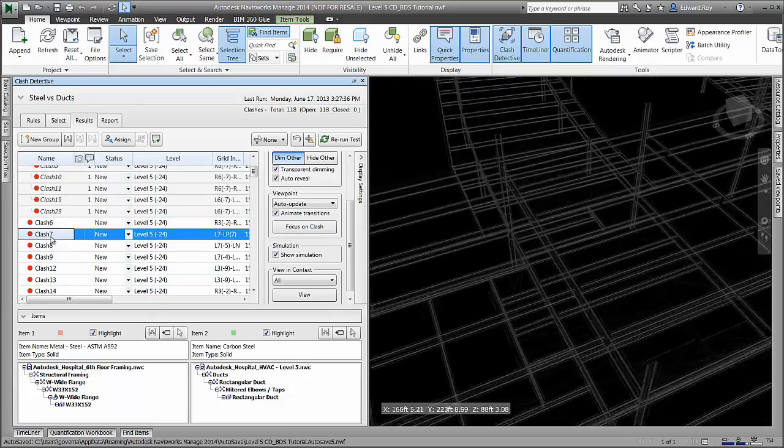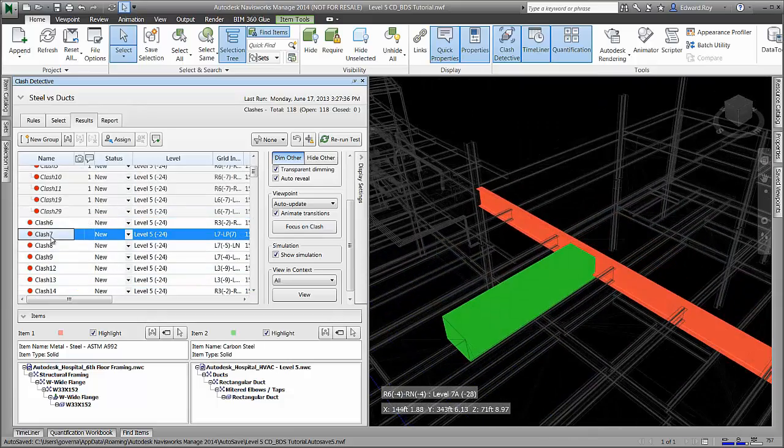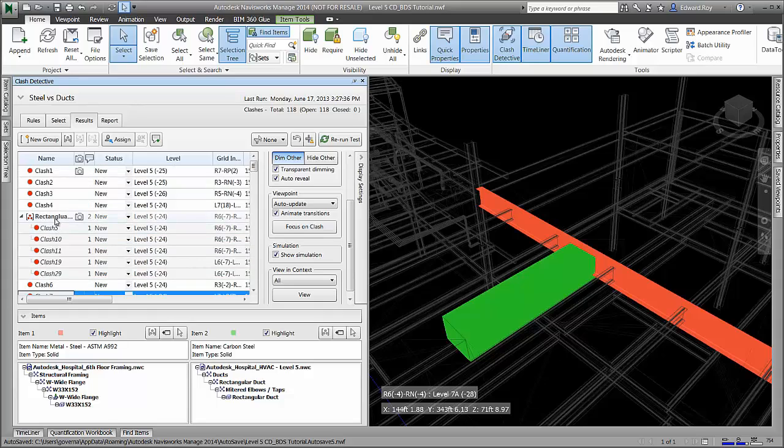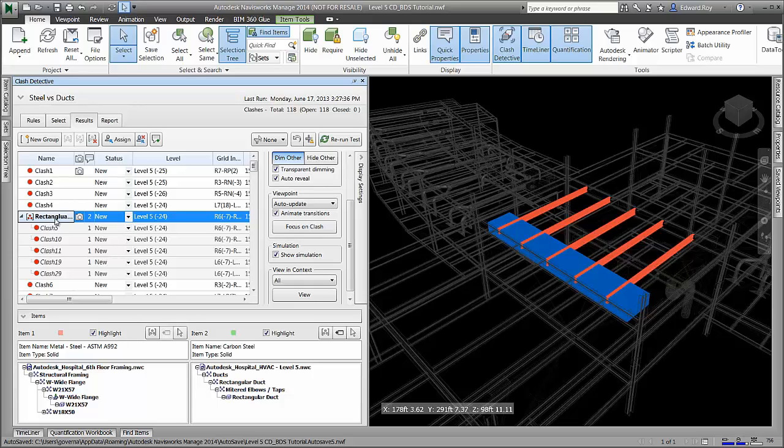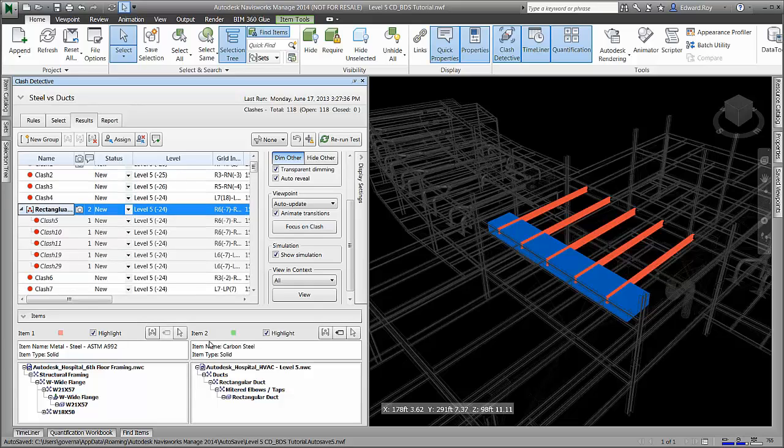So I would keep going. I would do that same grouping again. But what I'm going to do is come back to that one clash. Now it's time to start to resolve these clashes, and I'm going to use the switchback functionality built into Navisworks, which again is an important part of the workflows using Building Design Suite. We'll use the switchback functionality here by choosing the switchback for the correct object, in this case the duct. And in the background, Autodesk Revit is being opened up for us, and it's loading that model